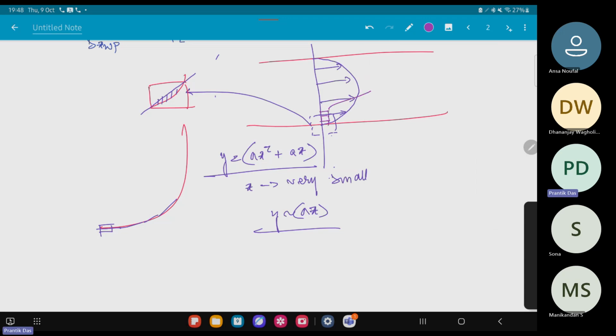But in the center region, the gradients are not so high, so there we can consider the cells to be larger, because the gradient decreases toward the center line of the pipe. Obviously in the middle, du/dy equals 0, since that's the maximum.